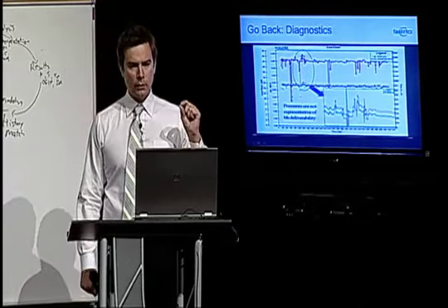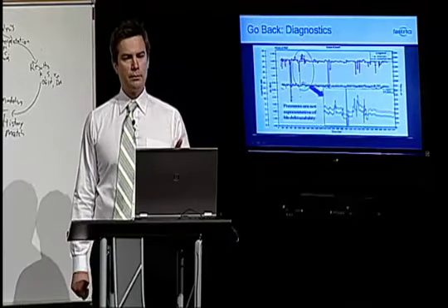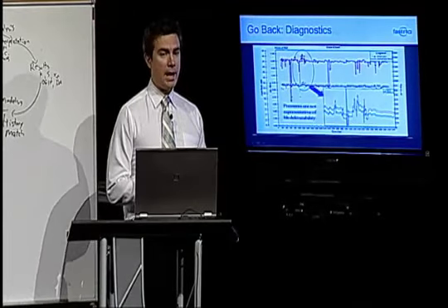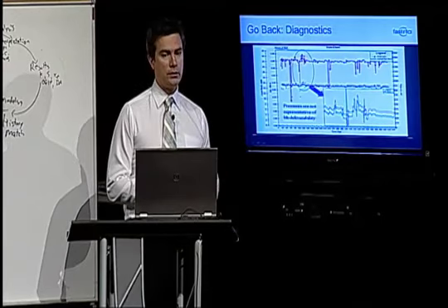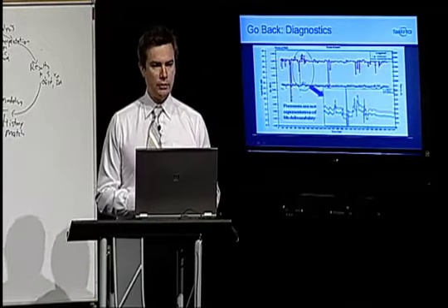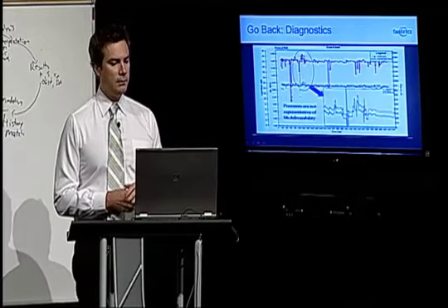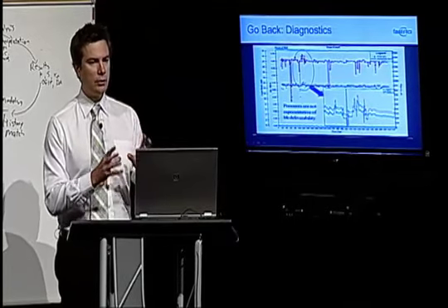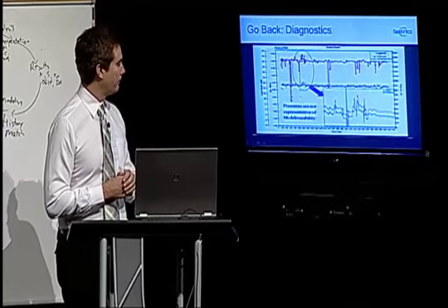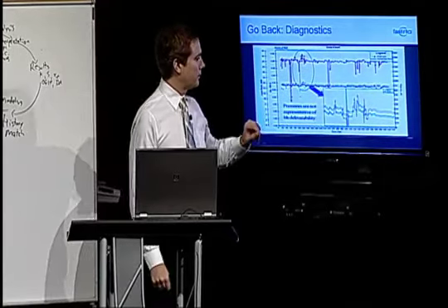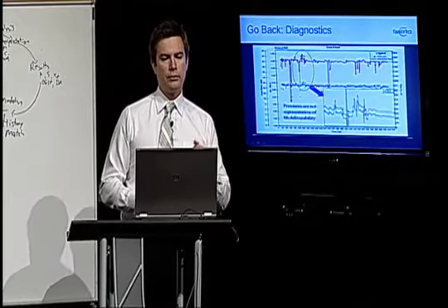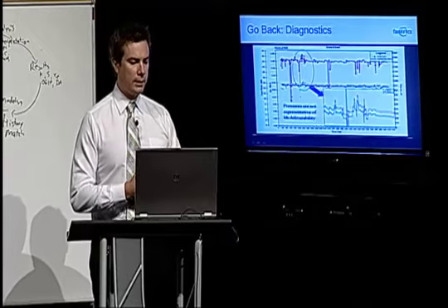If you can get the quiet side measurement, in other words, the annular space between the tubing and the casing, in a well that does not have a packer in place, so we have a direct connection to the sand face, that's better. That's an even better measurement than measuring it on the tubing head side. But certainly if there's any choke or anything in place, we need it to be on the upstream side of that choke. So that diagnostic will tell you that right away. It's easy to see immediately whether rates and pressures are working for or against each other.